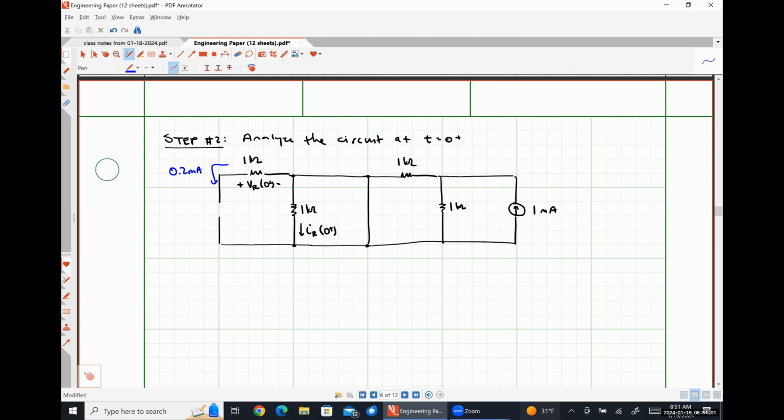Does the voltage drop across the inductor matter? No, it can be whatever it needs to be, okay? So at this specific instant in time, our inductor is actually behaving like an ideal current source. It has some fixed amount of current flowing through it. It literally cannot change, because for it to change means that we would have to create or destroy an infinite amount of charge or transfer an infinite amount of energy.